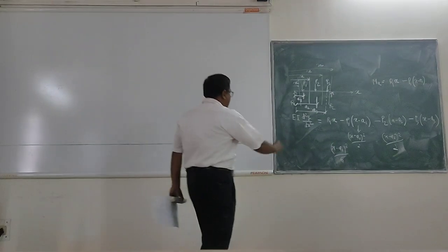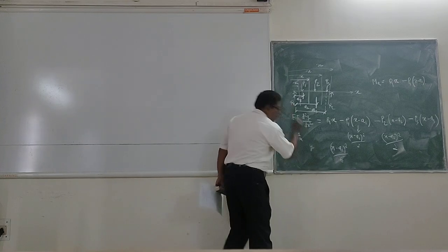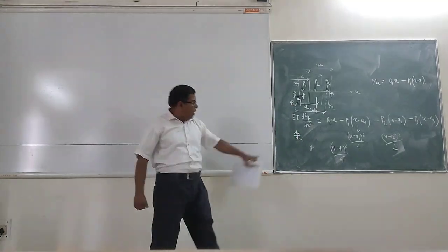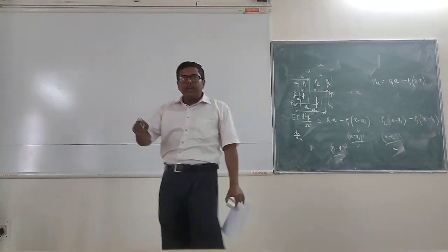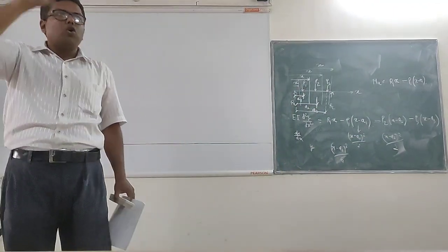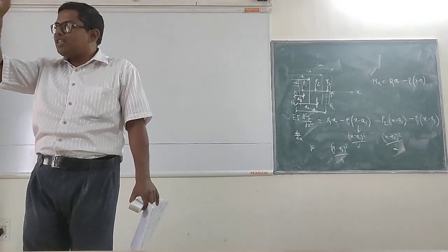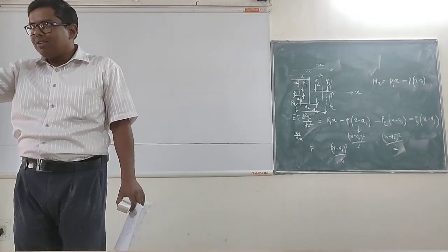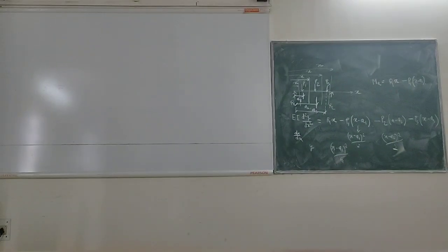If I am now considering the dy/dx term or the y term, these terms will come. Although they are becoming whole square and whole cube, the identity of X minus A1, X minus A2 remains. Now consider X equal to 0. What is the boundary condition for a simply supported beam? At X equal to 0, Y equal to 0.